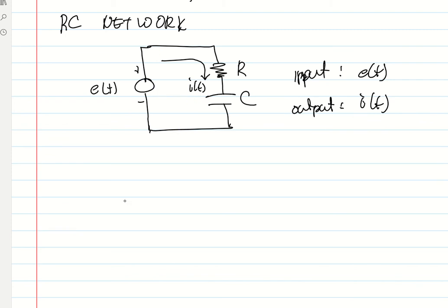We start with positive E, then minus the current multiplied by the resistance R, then minus the voltage across the capacitor. We already discussed this in Circuits 1: the voltage across a capacitor, the voltage across an inductor, the charge, and so on. You can review them. The voltage across the capacitor is equal to 1 over C, the integral of I of t dt, from 0 to t.